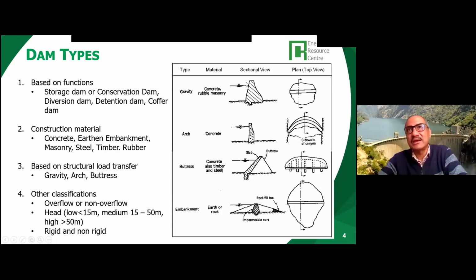This is the hydraulic pressure, hydraulic load. Based on the depth of the water, it is basically triangular at the base, its head multiplied by gamma. Gamma is the specific weight of water. Gamma H is the so-called hydrostatic pressure. This is counteracted by the weight of the concrete structure. So this is what is known as a gravity dam.